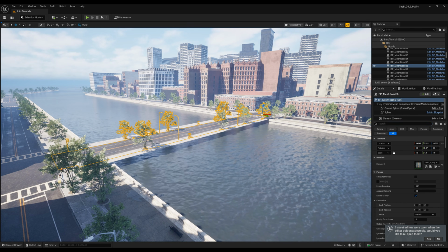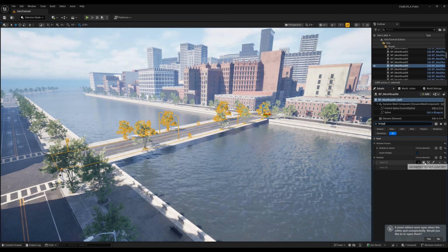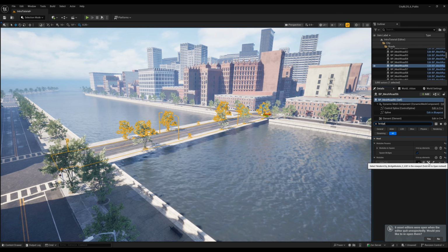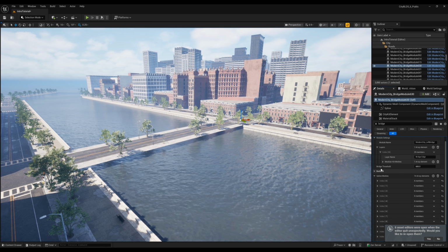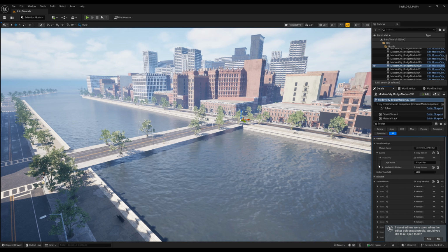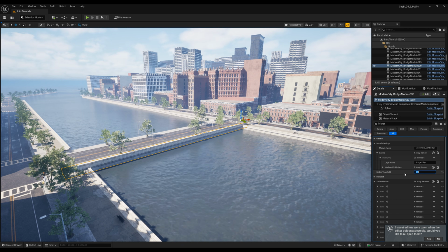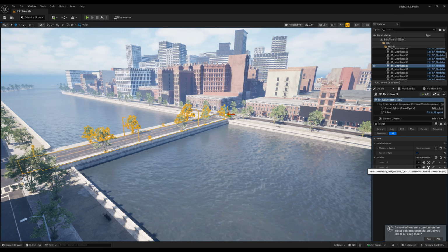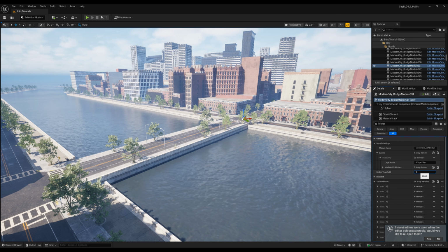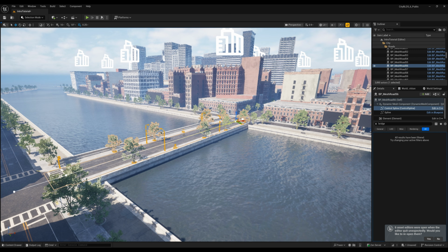Let's convert these roads to bridges. We can do this by selecting the Bridge road modules, which only appear in areas that are elevated, and lower the threshold so that the entire road is treated as a bridge. I'll also add another point to give it some slope.